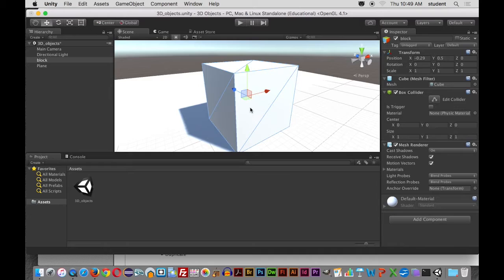You see? Yeah. So when I say this is the face of an object, this is what I'm talking about. If you were able to extrude or pull in or pull out, if you were able to grab the face of an object, you would most likely sometimes be grabbing just a triangle. I think if I wanted to grab this whole side of it, I would have to select this face and this face, so it's these two triangles, and then click and drag it, pull it in, pull it out.